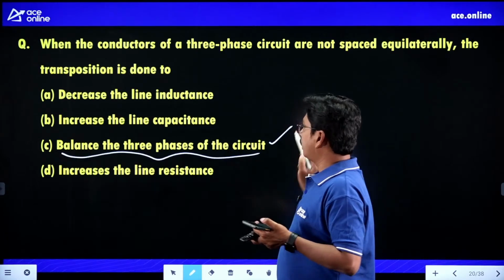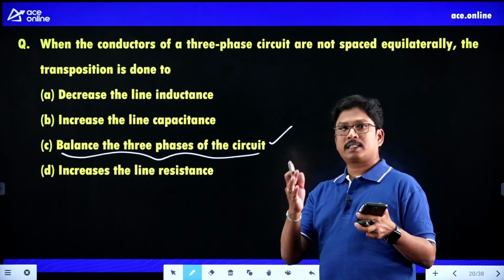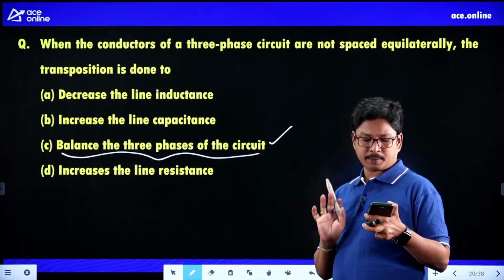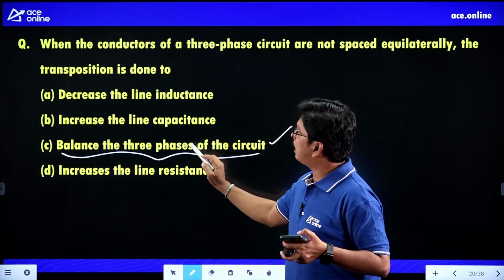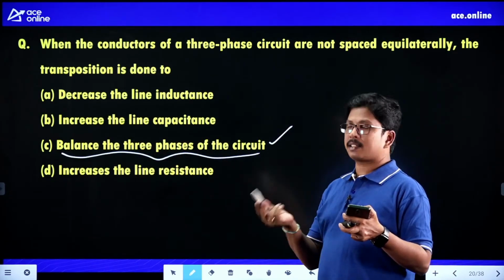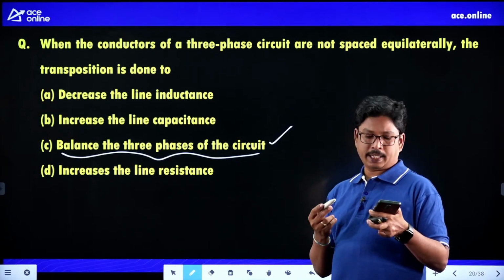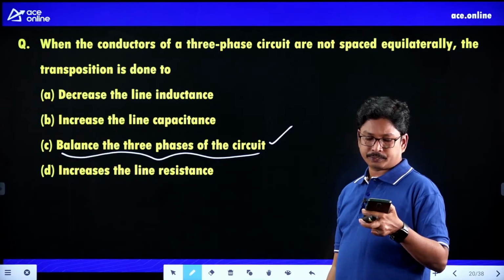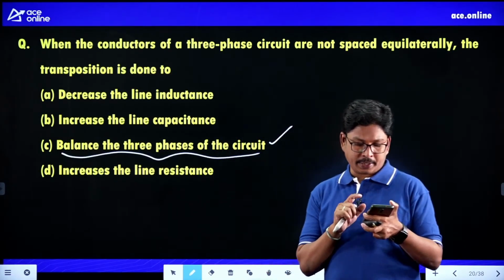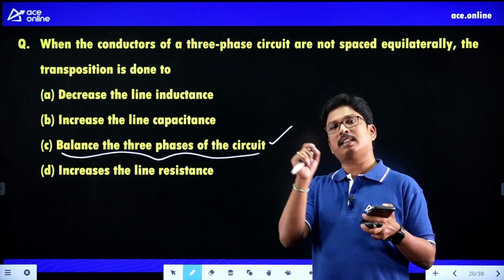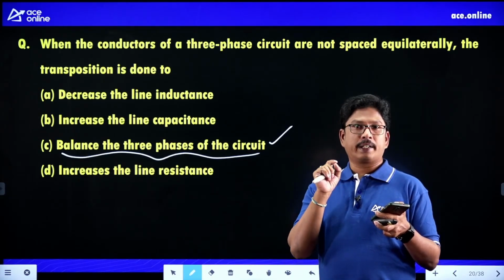So now please check it. It is to balance the voltage drops in the transmission line. Whenever we are balancing the voltage drops, the three-phase system can be balanced. And Hari Prasad, option A, it can reduce, right? The main purpose of doing transposition is to balance, and the extra advantage is that it reduces the overall reactance of the system. It's not going to reduce the overall reactance actually. Yes, very good, radio interference. We can reduce the radio interference by balancing the three-phase system. So when the three-phase system is balanced, then only the radio interference can be eliminated.